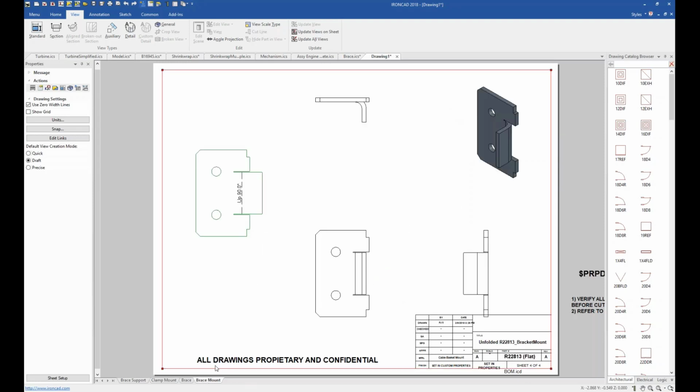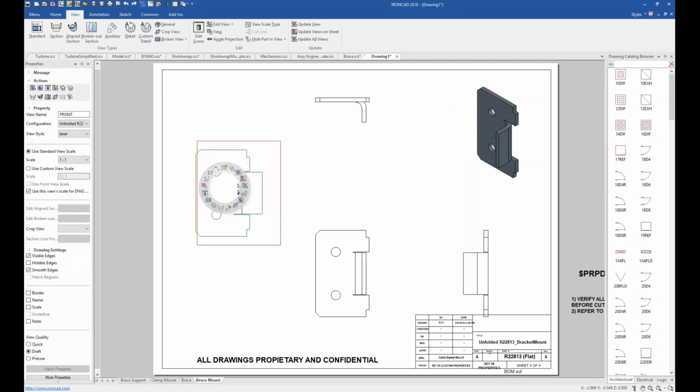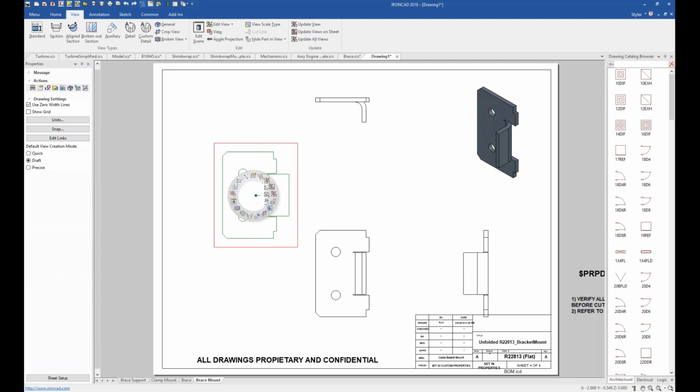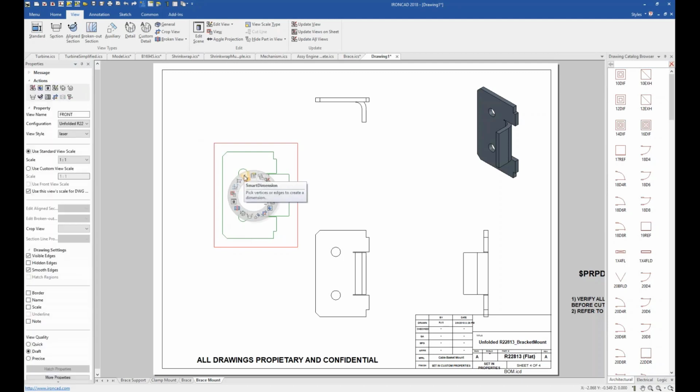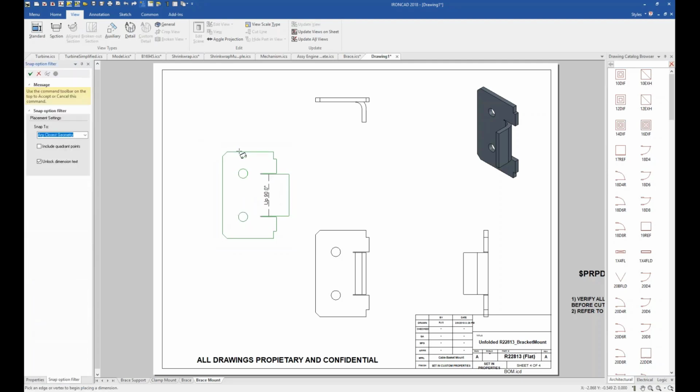We can also use it on our detailing process. So when you click on a view, for example, let's just move this over a little bit. If we click on our view, we can see other commands for detailing or dimensioning the file. So in this case, we'll just go ahead and do smart dimensioning, where we can click 2 points, place our dimension where we like. We can click another area on here. Say we place a dimension there. For our small dimension, we can create one for a point here. We can tab that over to get whichever one we want and place it.